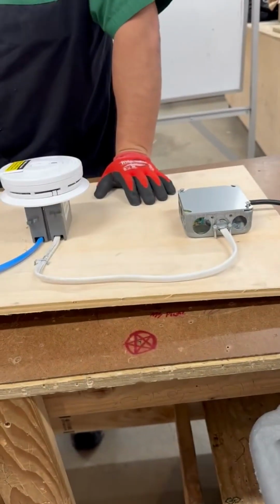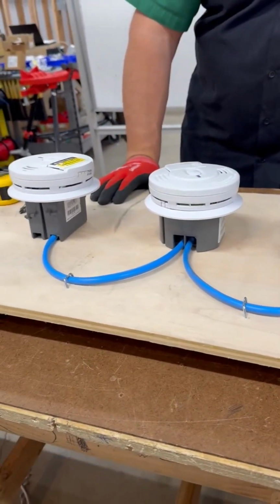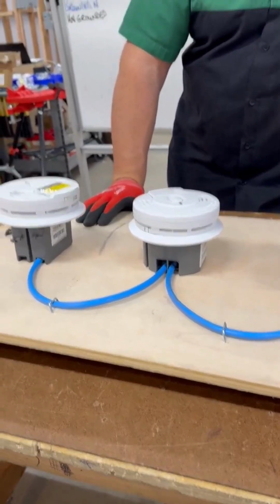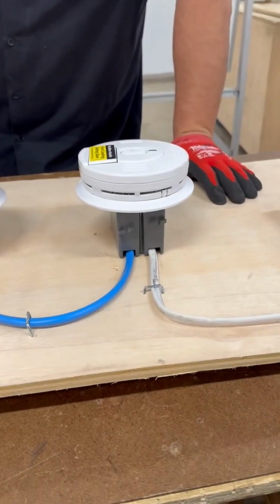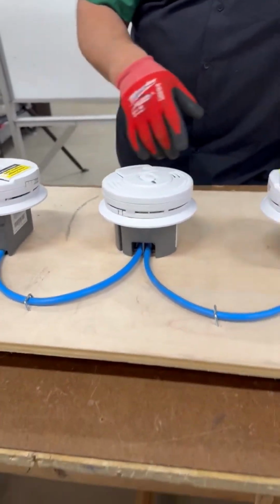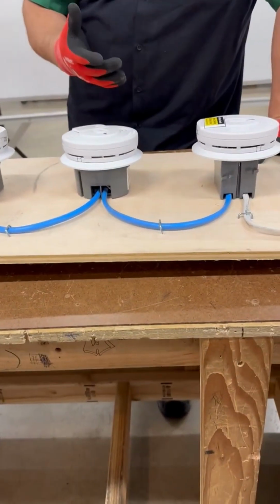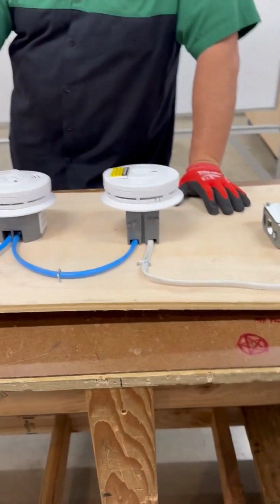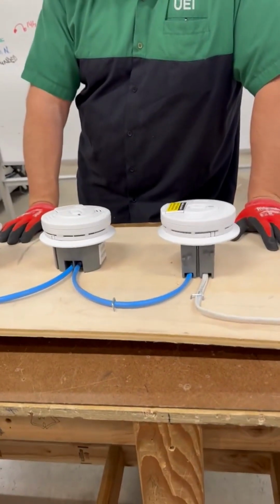I just did one not too long ago for a neighbor of mine. And every time, she's got the sealed battery type, we have the front door loading type. But the sealed type automatically goes into a short alarm burst every time the power goes out to the circuit. At this one, the one thing that I noticed when we hit the switch is it chirped. And the same thing when we provided it power, it chirped again. And you can hear a chirp here and there. And again, that's going to be the battery, because these might have been sitting around on the shelf.